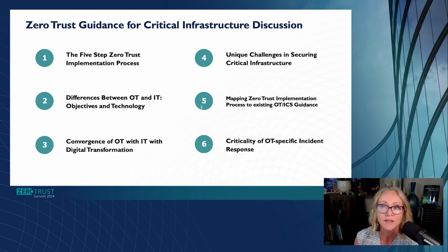We talk about when you get into building a zero trust architecture, where can you position those policy enforcement points or those monitoring areas so that we can funnel traffic to get very high fidelity reporting in the OT environment. We talk about different ways to segment. Our normal things we do in IT, we've got access control lists at layer 3, we've got VLAN constructs at layer 2, you've got physical segmentation and the, I'm going to air quote, air gap that doesn't really exist anywhere. But then we have other tools in OT that might be applicable.